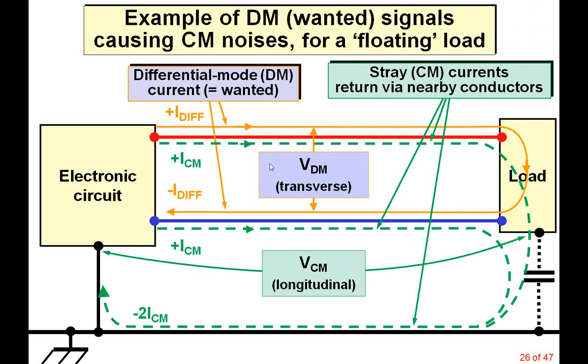And the common mode current flows down both the conductors and back through the chassis or ground or metalwork or something. Now in practice, of course, the red and blue wires are close together, and this is some distance away. So the common mode loop is generally much larger than the differential mode loop. That's why, even though it's typically between 1,000 and 1/10,000th as strong as the differential mode current, it causes most of the interference.